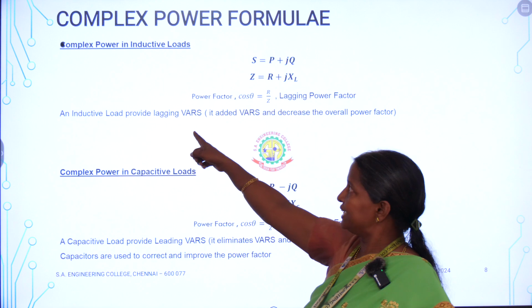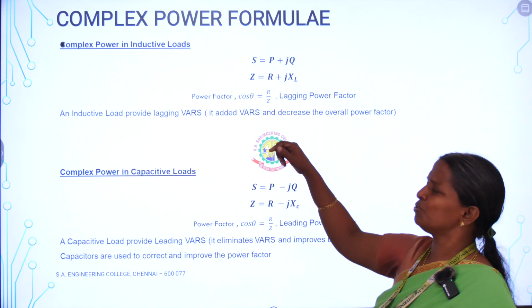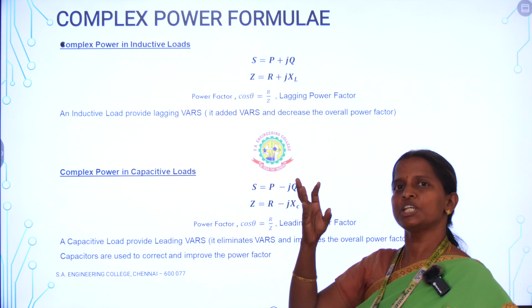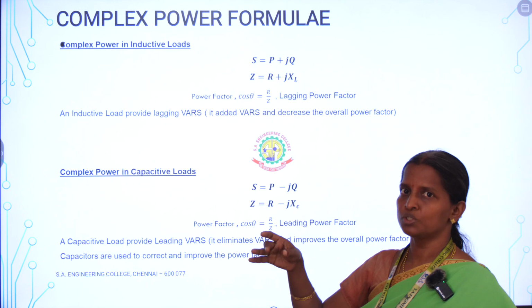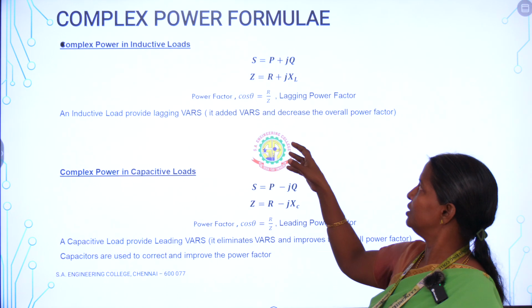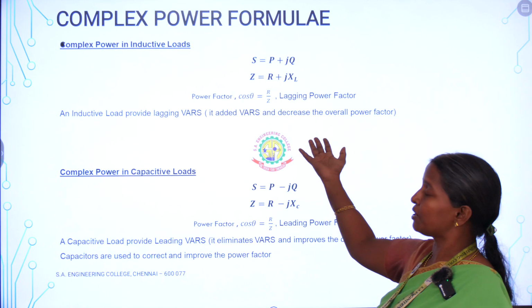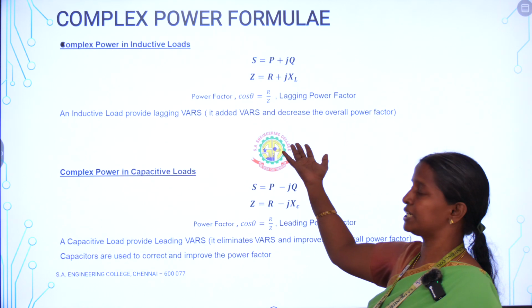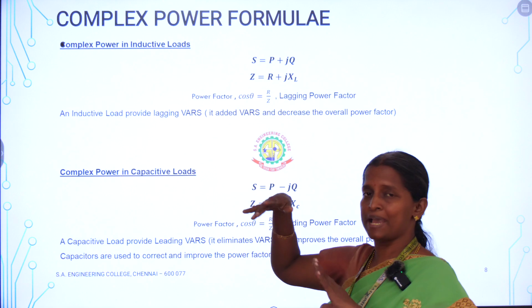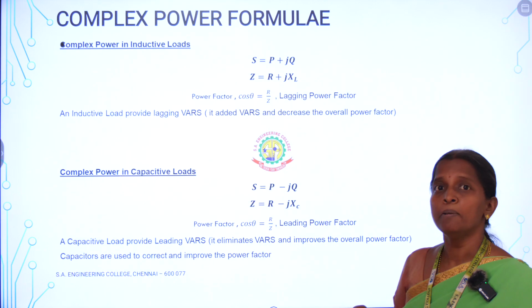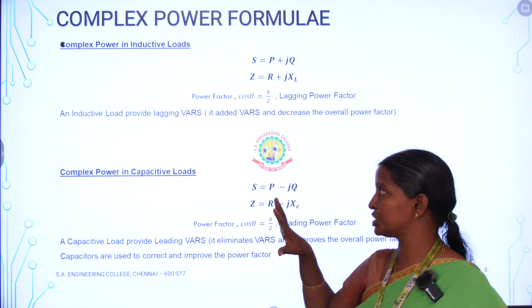And the inductive load will give the lagging VAR. So what is VAR? Voltage ampere reactive. So that is what VAR is. So it will decrease the overall power factor of the circuit, power system. It will reduce the power. If your inductive load is maximum, it will reduce the power factor of the overall system.